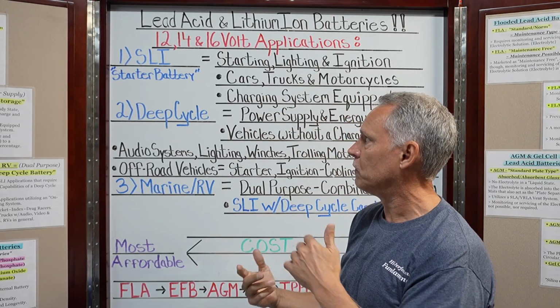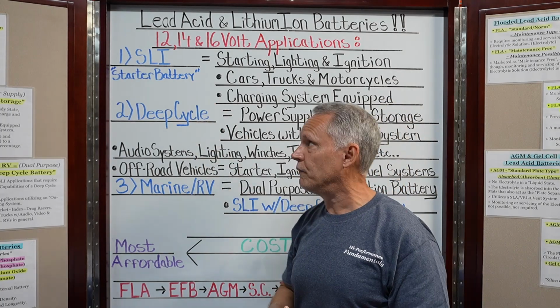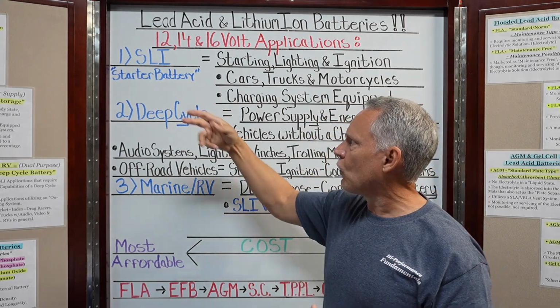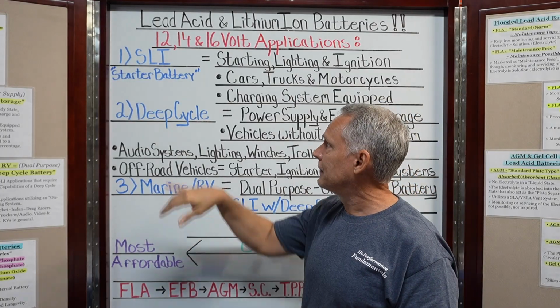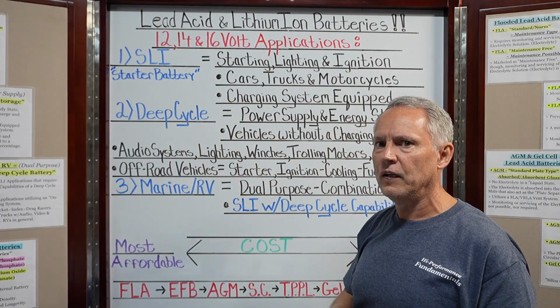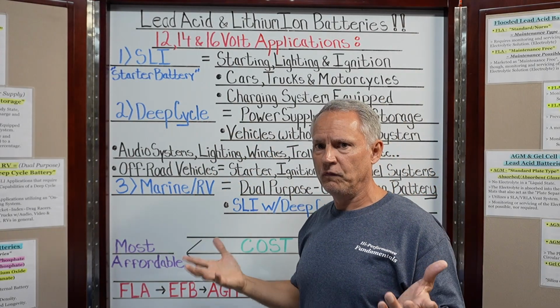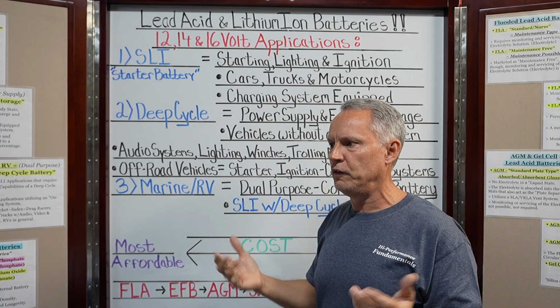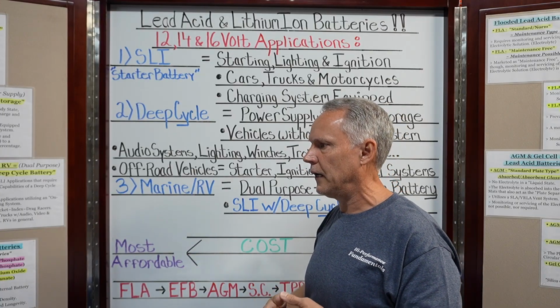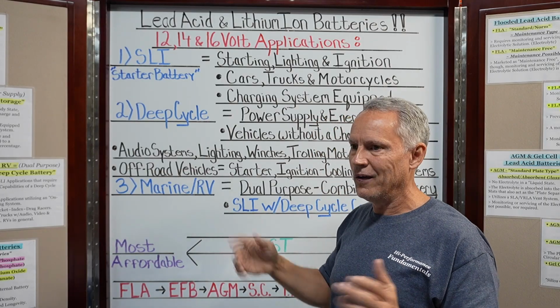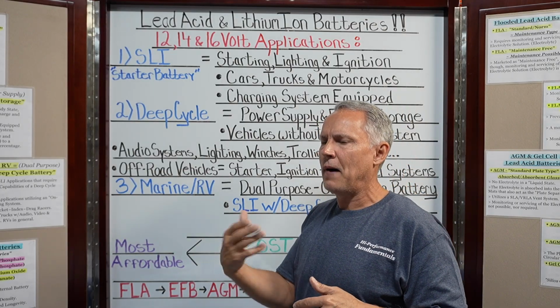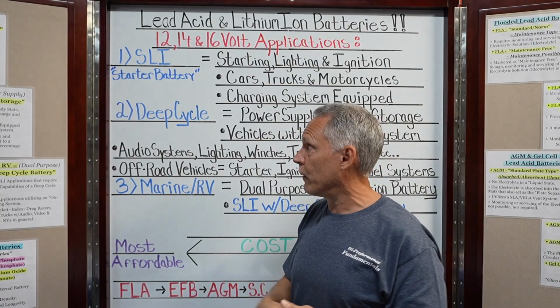The charging system in vehicles is what the vehicle actually runs off of. Once a vehicle is up and running, it's no longer really utilizing the battery to power the vehicle. You may think it is, but it's not. It's actually the alternator or the generator in the vehicle that's powering the vehicle, creating the electrical energy for the ignition system, the fuel system, the onboard electronics, radio, lighting, whatever. That power is coming from the alternator or the generator and not the battery.